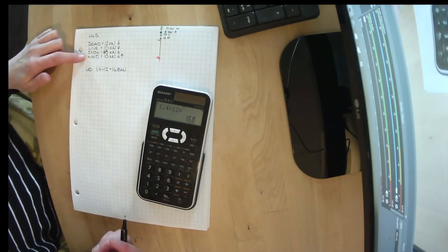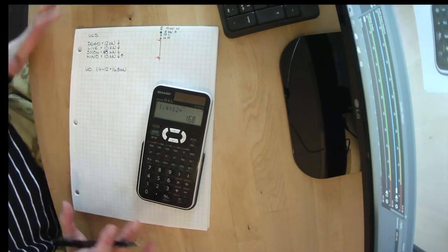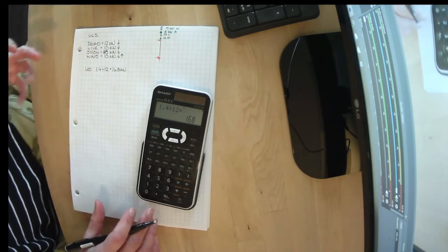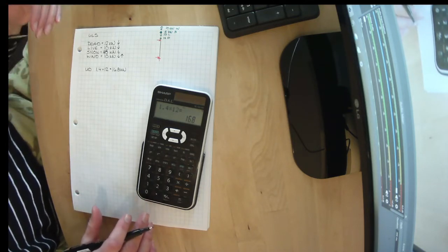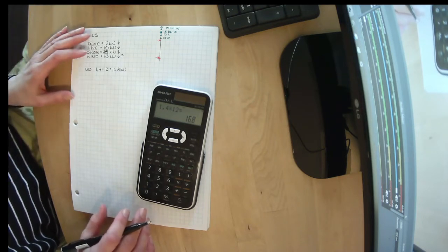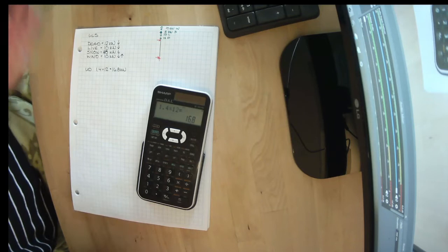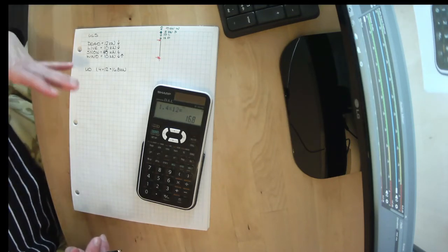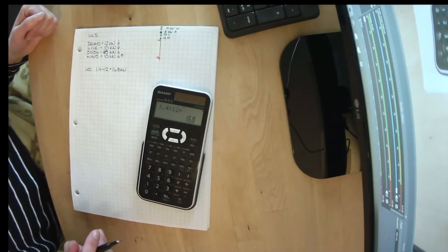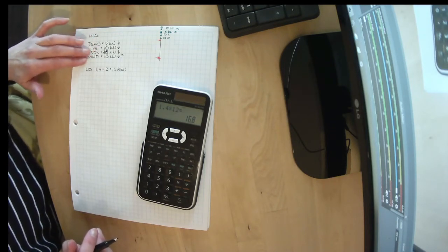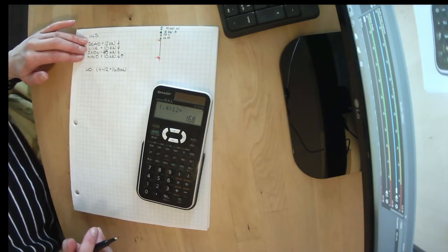And then wind load, we don't quite understand how columns work with a wind load yet, but you can trust me that it very much can act as compression or tension in a column. And we know it comes from climatic data, and it has to do with it blowing on the building. There's also the option of roof suction. And we need to figure out the different possible combinations of all of these loads.